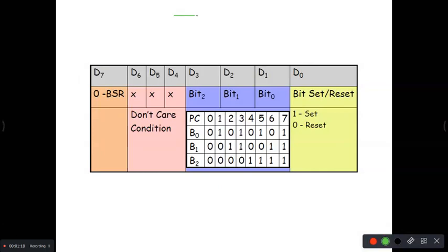First I will draw your 8 lines. 1, 2, 3, 4, 5, 6, 7, 8. This is your PC0, PC1, PC2, up to PC7. Totally it is your port C. By using only the control word, we use only the control register to make these individual lines on and off. Using the control word only, we'll try to make these 0 and 1.